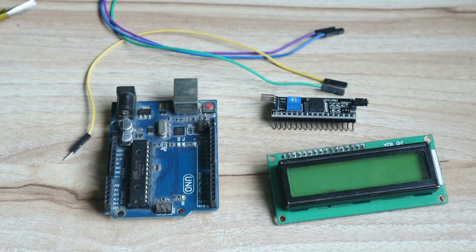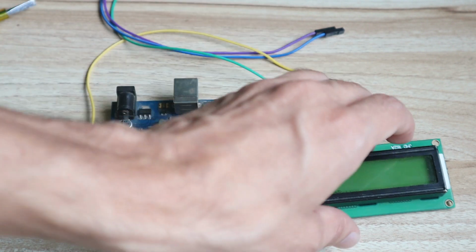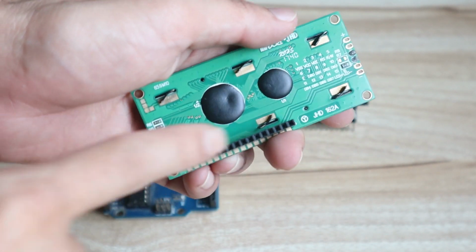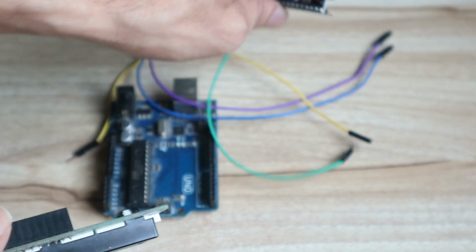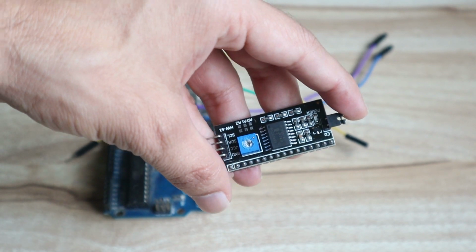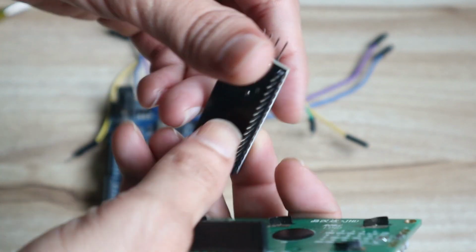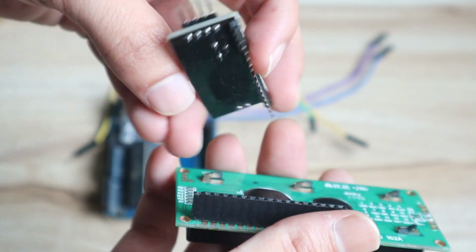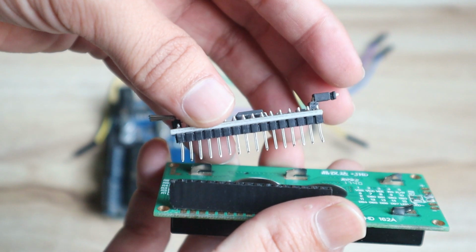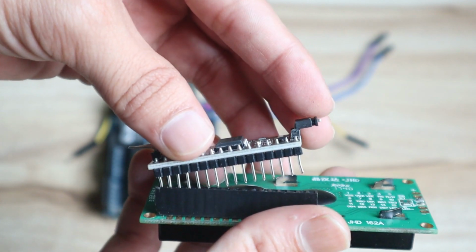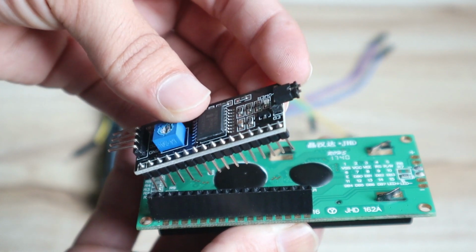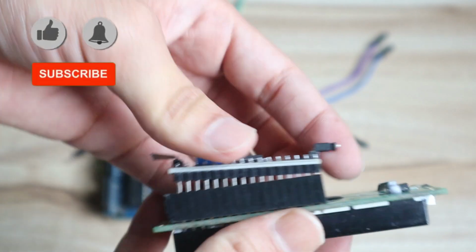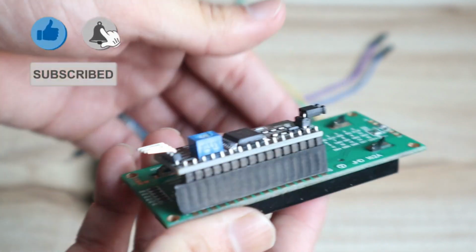Okay, so we will see in depth from the starting. Basically your 16:2 display has 16 pins here, you can see, and those 16 pins you have to connect with the i2c module. So this is the i2c module. How to connect? Just like this, and from point 1 you can connect this, sorry, like this. From point 1 you can connect this till your 16th pin, like this. Or you can use a breadboard also to connect these pins, no issue. Only point